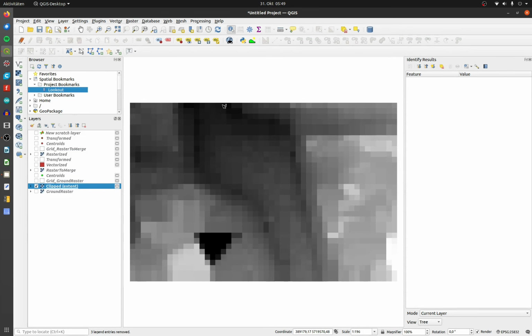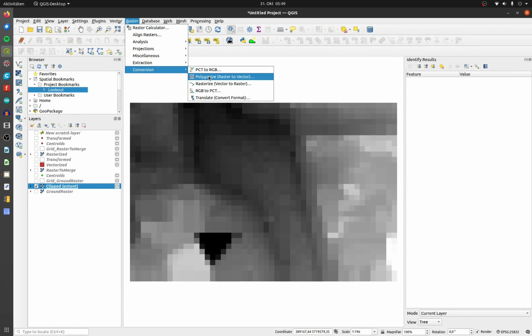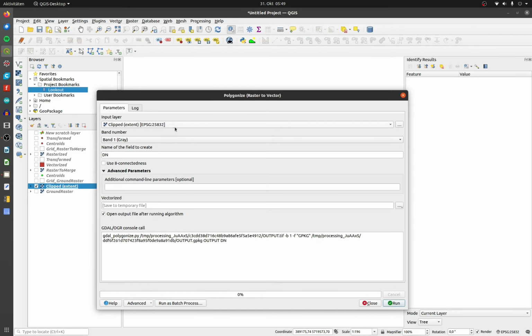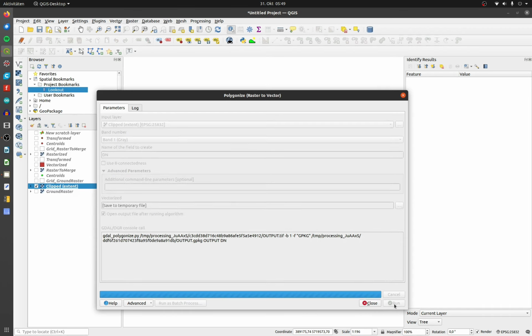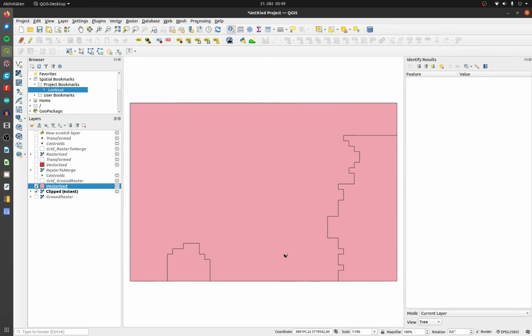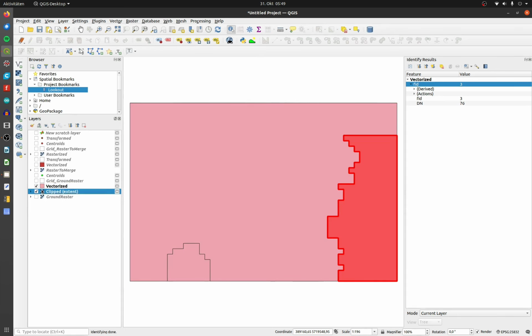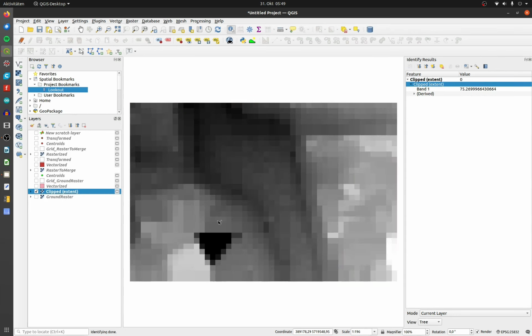Sometimes the conversion from raster to vector creates big connected cells with the same height information. It happens when the difference in height is very low between cells. Like in my example, I get 3 big connected cells back. The height of the example is about 75 to 76 meters and changes only in the decimal area. There's a trick to deal with it.